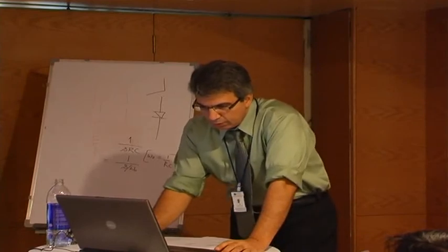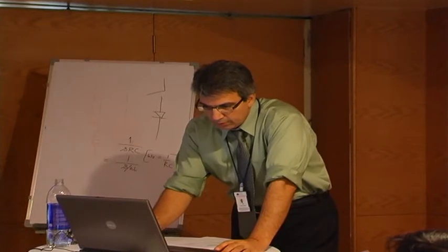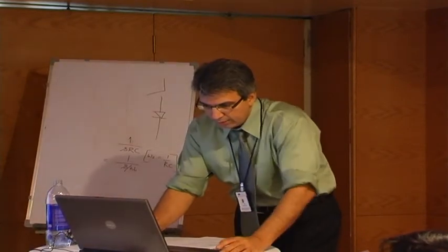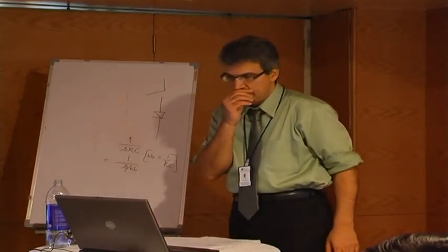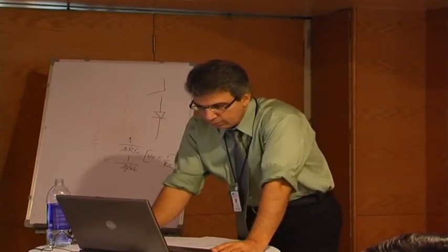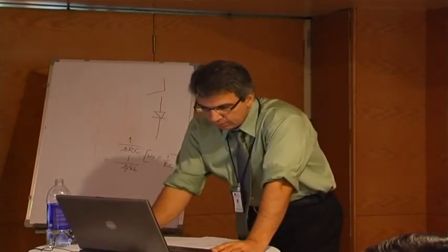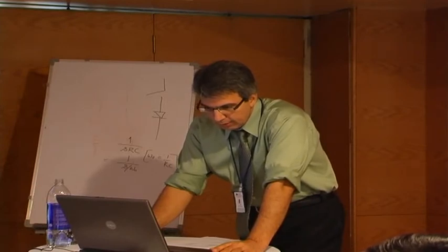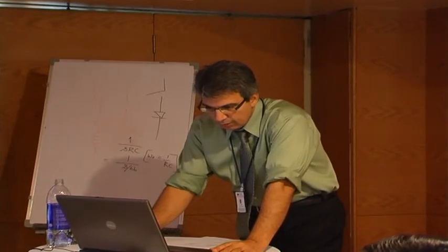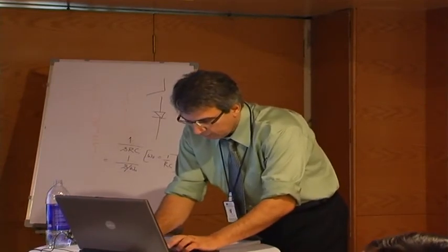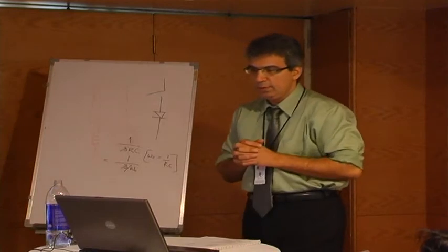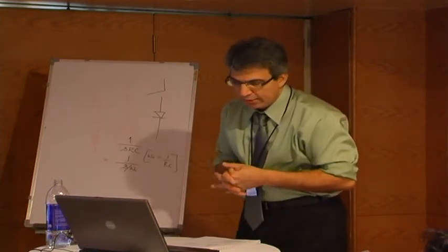And I can also add phase 2. I can add another plot and say trace add IL2. I can also change the color of this. And then another trace, or I can also add another plot and add, let's say, IL3. Okay.